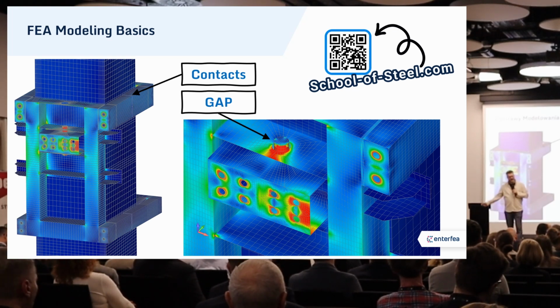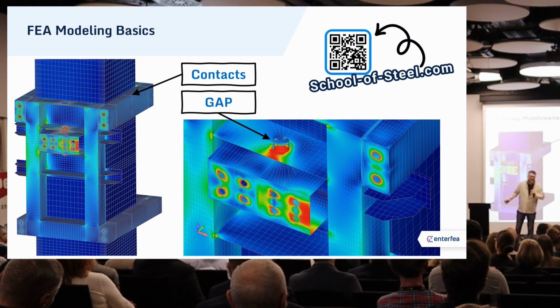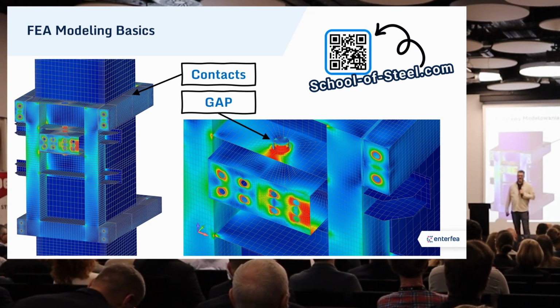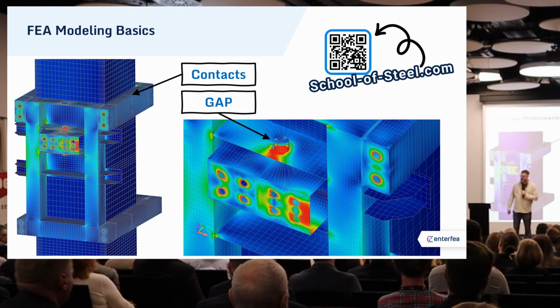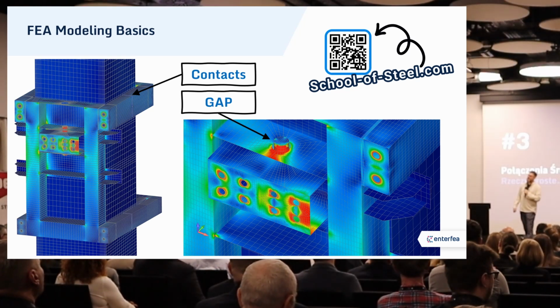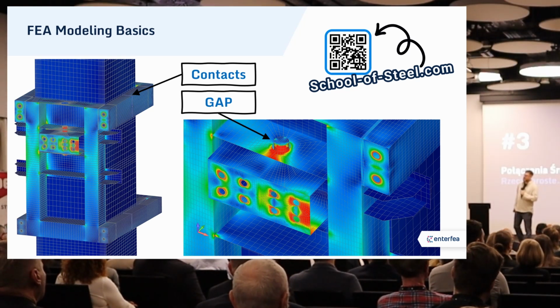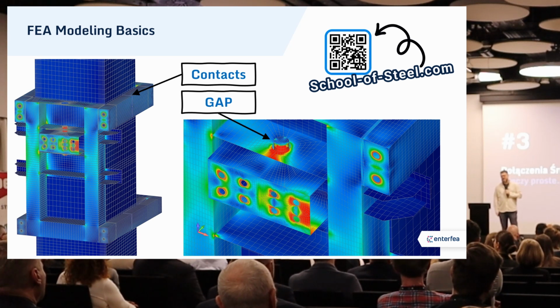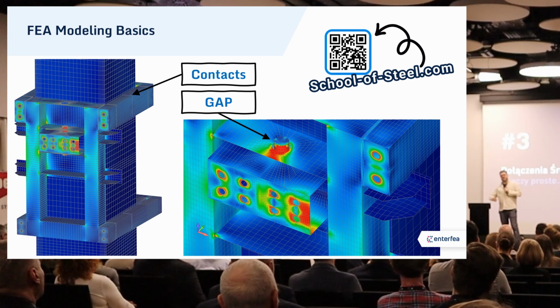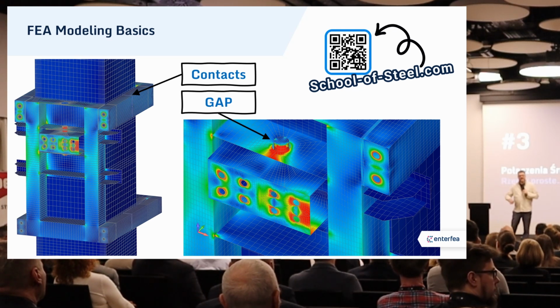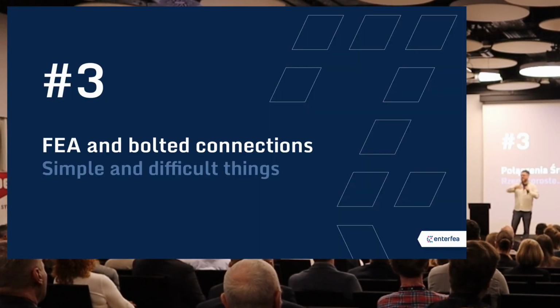And essentially, if you connect all the nodes of one plate with the corresponding nodes in the other plate with compression-only elements, you essentially faked contact, and that is a nice approach to it. I did several models that way before I had a solver that actually used contact.